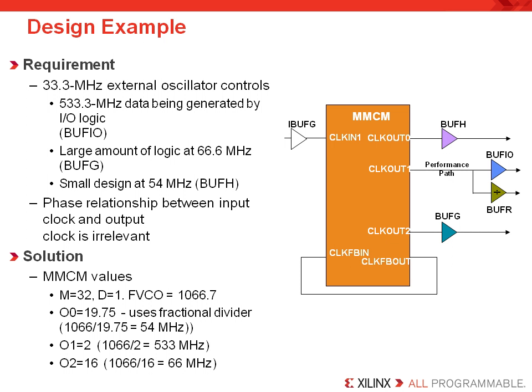Not to mention the advantage that you have a fixed number of MMCMs and PLLs in your device, and perhaps you don't want to waste another MMCM to generate one of the clock signals. So in this example, since we have 3 different clocks to generate, we probably want to use as high a VCO as possible, since this will give us the most flexibility.